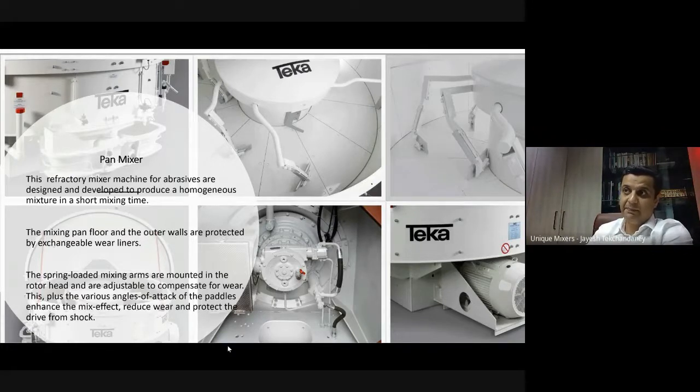We discussed the plowshare mixer being used in refractory industries. We discussed the double paddle mixer. We talked about the Sigma mixer in tap hole clay. We talked about the gravity blender, the drum blender being used for some applications. So besides the mixers that we discussed, these are the other